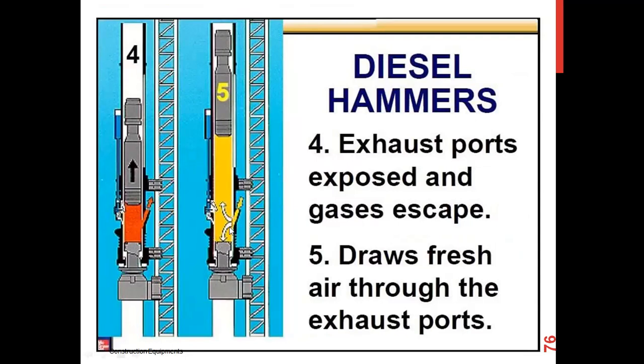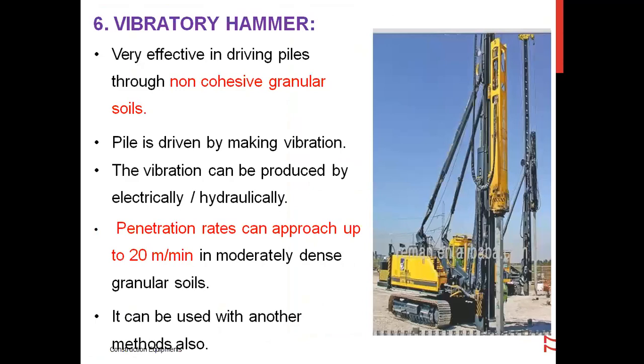These are the ports provided for the escaping of gases. The diesel hammer draws fresh air through the exhaust ports and pushes the exhausted gases out through these voids. The vibratory hammer is very effective in driving piles through non-cohesive granular soils.